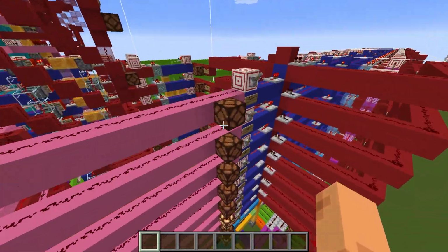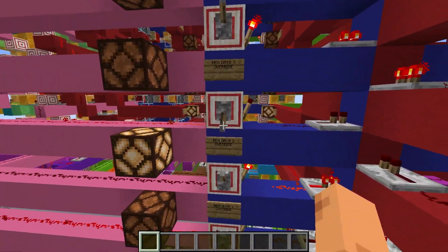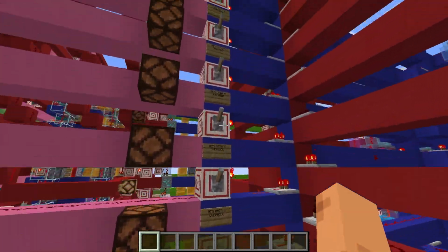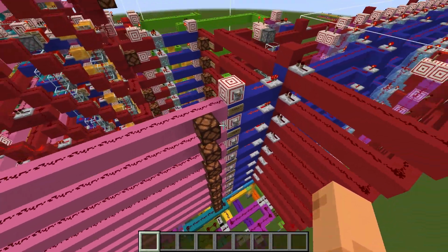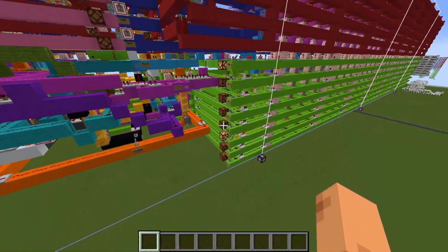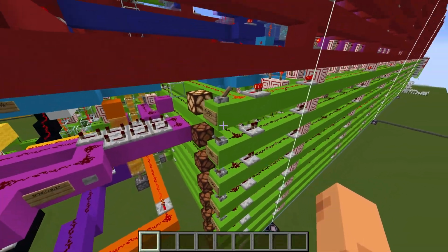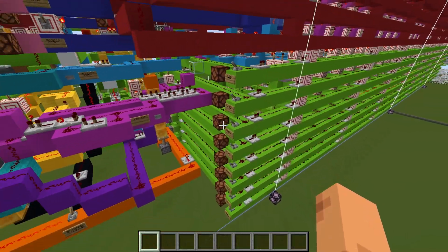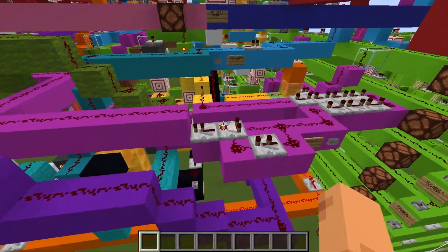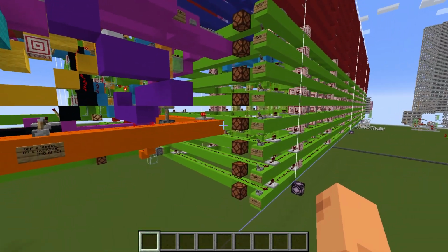Alrighty. Make sure that stuck. Good. Make sure to disable the overrides, otherwise we will be corrupting our data as we execute the program. It's important to disable the address lines before we start execution, because otherwise we will also corrupt the address lines, which will mess everything up. All right, so let's start this program now.